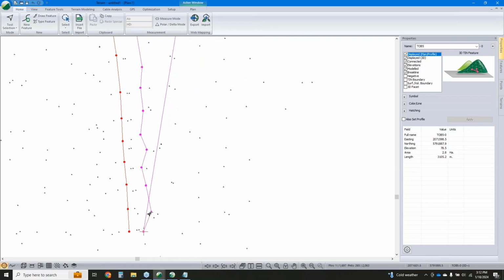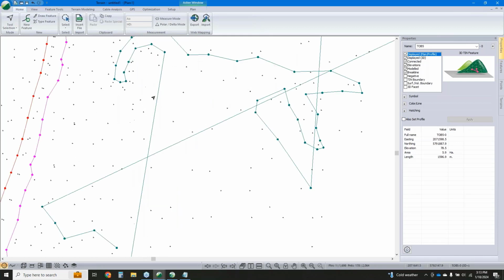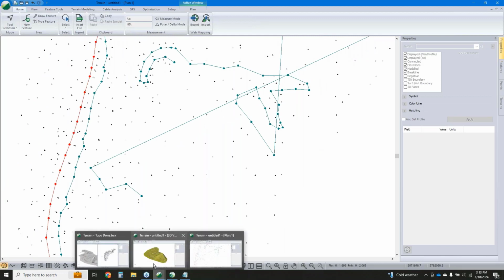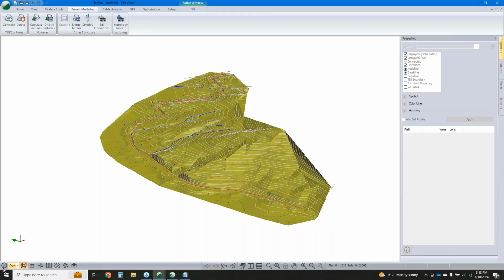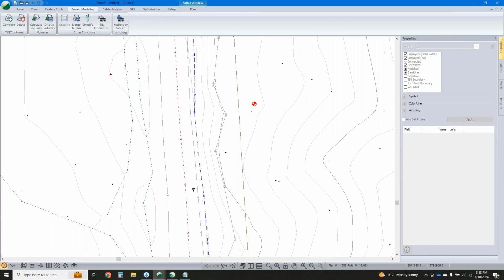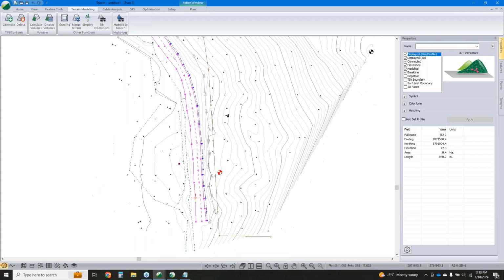So in here, if I brought that in and I didn't want to just re-import the data, well, I can use a bunch of functionality to edit my line work, like break at current point. And I can go to the other end of this, break at current point, and we can split that up and work with that. So that's really the lion's share of it. There's functionality in the software to edit your points and modify your points, change your line work, connection order. If we want to just move a point, we absolutely can.